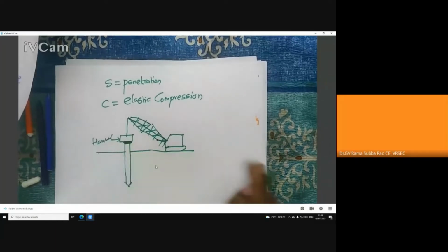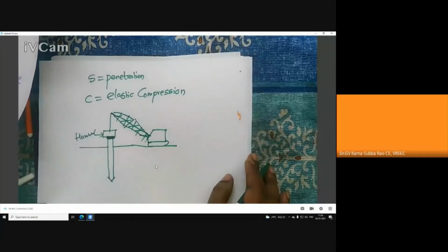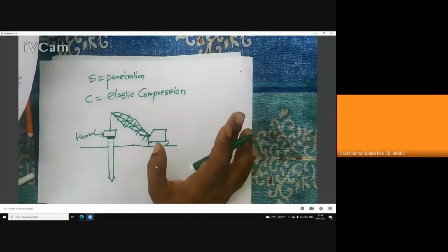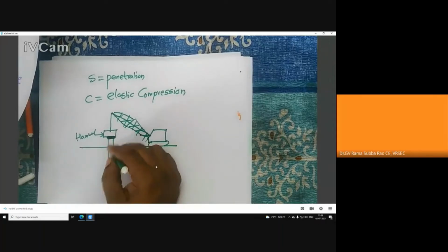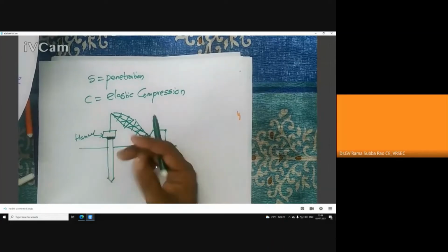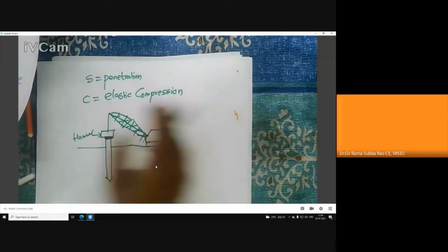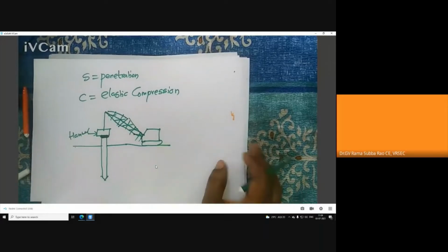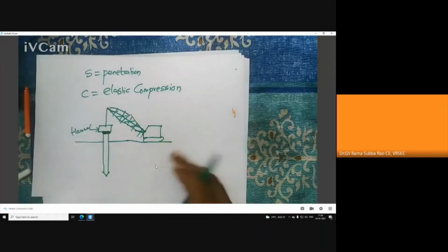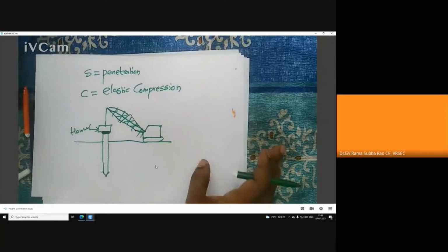In fact, the idea of Wellington is that he just applied the energy conservation principle. The amount of energy applied for driving the pile is equal to the pile load carrying capacity. I can tell you once again without any hesitation. In my masters, we used to read a wonderful book, Pile Foundations by Tomlinson. Tomlinson has clearly explained this, but the Indian books we generally read are not opening it up. They are just writing the formula and running away, but we will discuss it now.